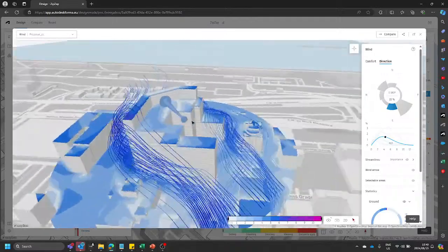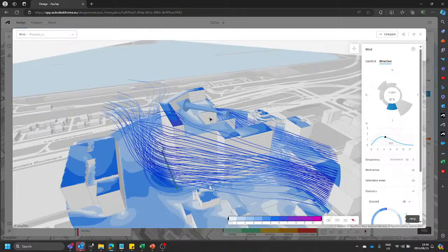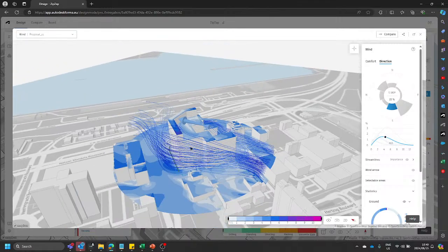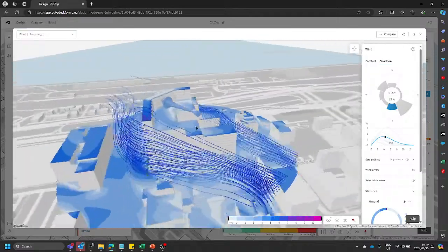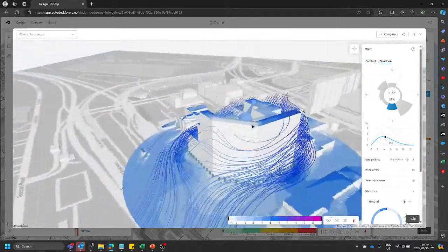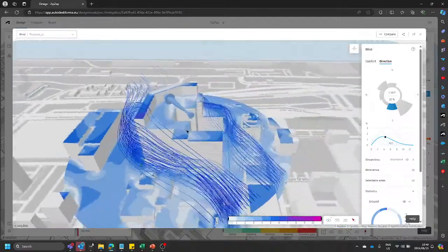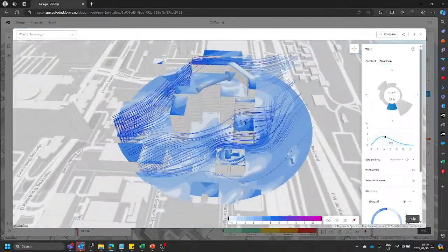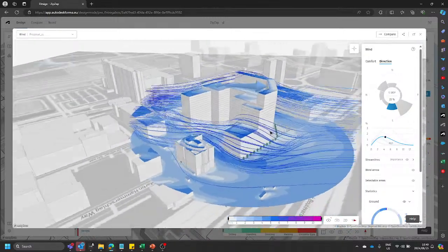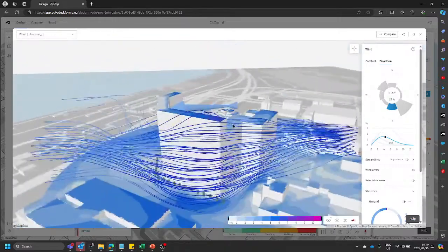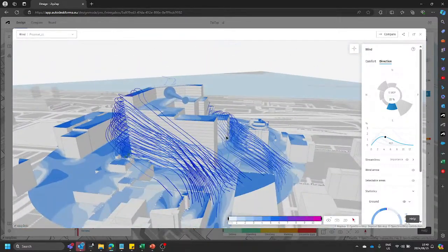And in Cape Town, for instance, we have to do ultimately a wind tunnel analysis with the CSIR, or National Standards Authority, basically. They've got a big wind tunnel with the entire city, and then they'll put your design in that wind tunnel and test it ultimately. But you stand a better chance of passing, at a lower cost. You know, if you come into the wind tunnel with a design that, based on these analyses that you've run for a while, you know is going to be better, then you don't need to worry too much about the wind tunnel failing or passing your design.